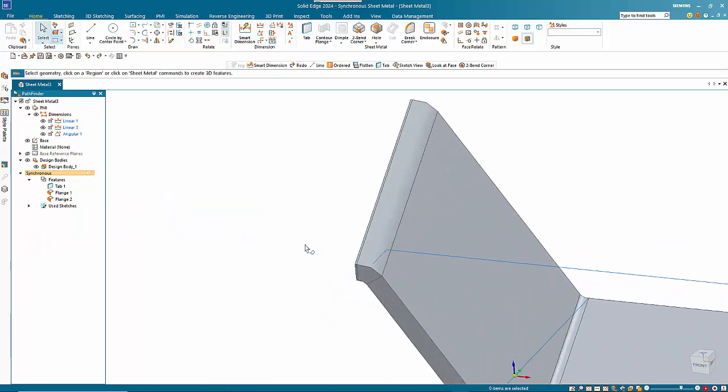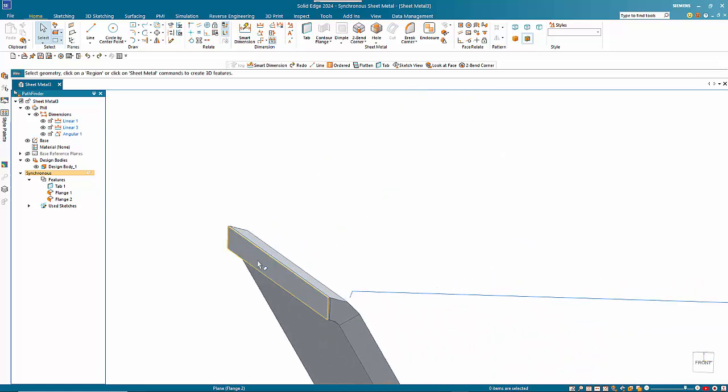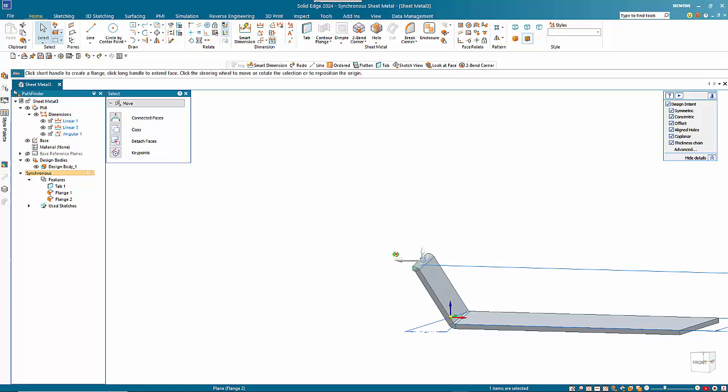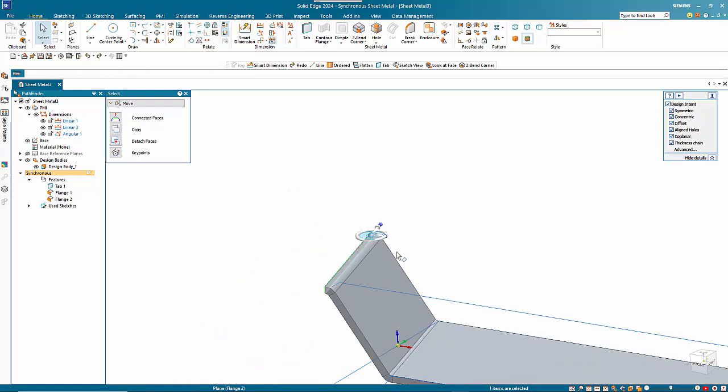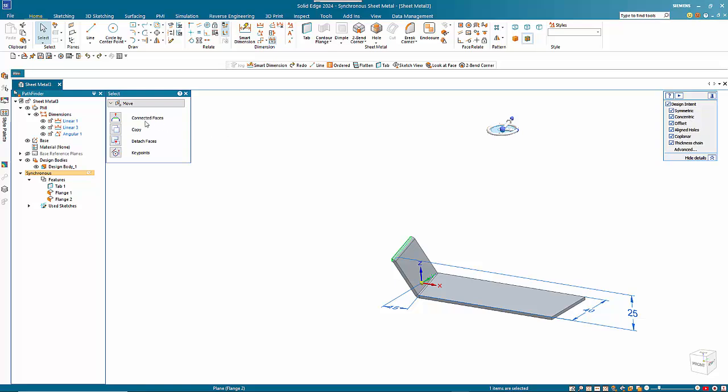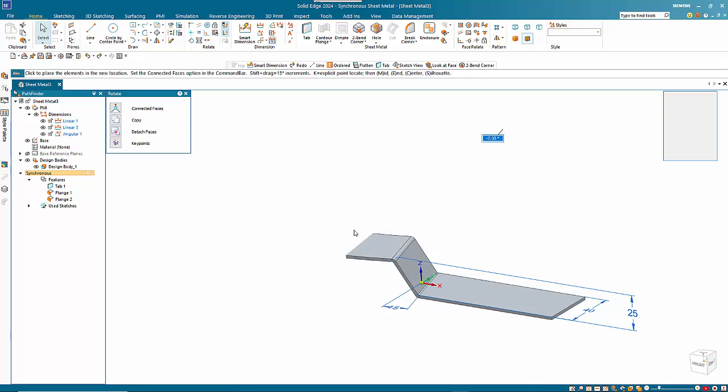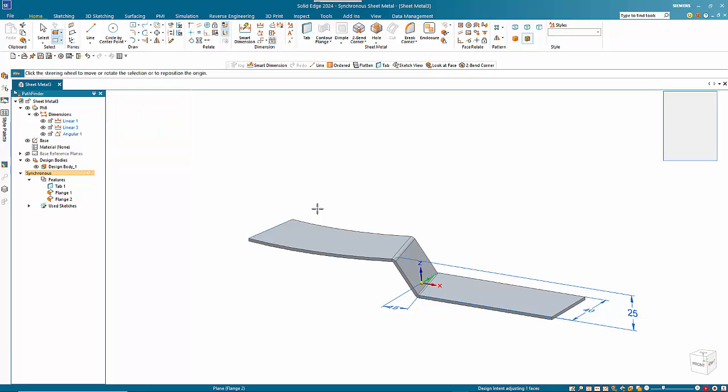Taking this back a few steps, we can also look at how we can create this using another method. We had an arc on here, so if I take that and move it to a point out here, hold the shift key down and click on the arrow, I can move this out, say 200, and click. Then if I change my options to lift, I can bring this round and create an arc on here. We can go 25 degrees on there and carry on as we were.